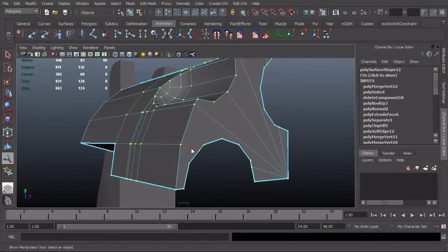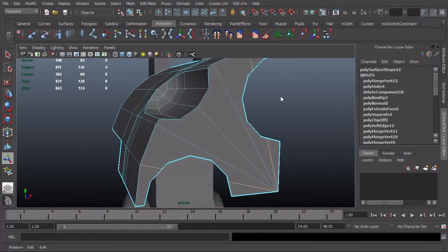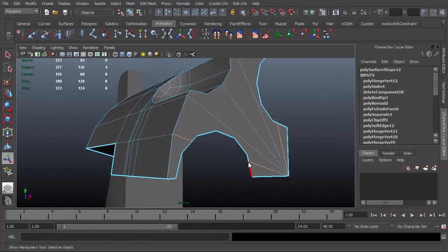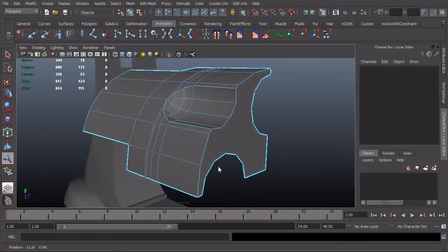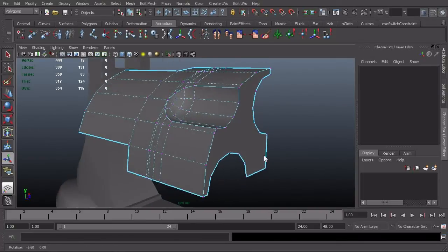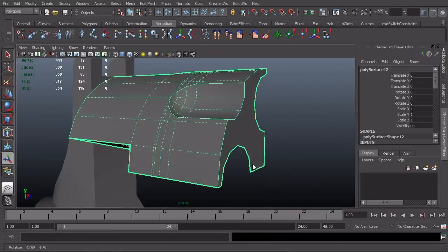And then I'm going to go ahead and delete out some of these extra spans. So all these guys here that are cutting through my mesh and adding extra points that are unnecessary, I'll just go ahead and get rid of those. And then these across here, I'm just going to delete those. So that'll just leave me with a big n-gon on the front, which is easy to look at, and because it's flat, it doesn't matter that it's an n-gon, it'll still triangulate just fine.